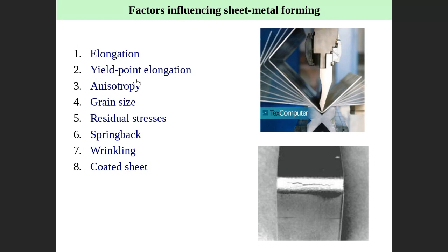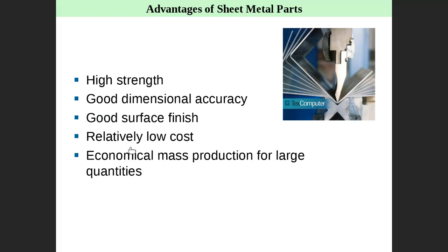sheet or whatever. This is the processing of the sheet which was done previously, before it comes to you. Whether this sheet has residual stress or not, whether this sheet was annealed or not, what the grain size is from the previous deformation, which is rolling. Is there annealing, recrystallization, or residual stress? All this information must be provided, so you know what deformation exists before you do more deformation as sheet metal deformation on the sheet, right?